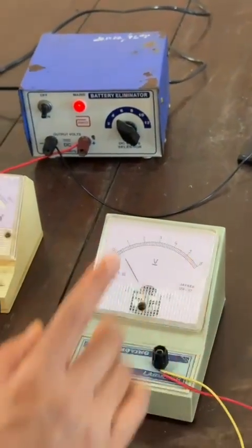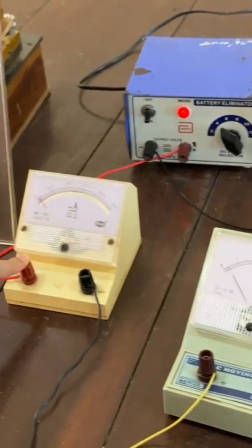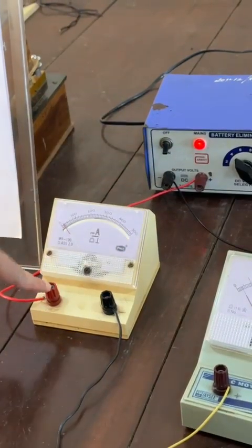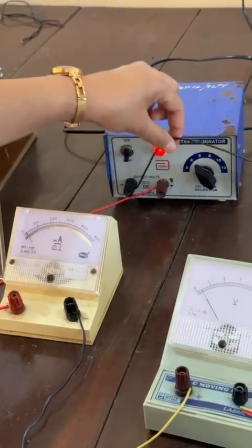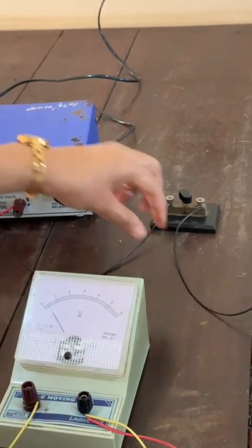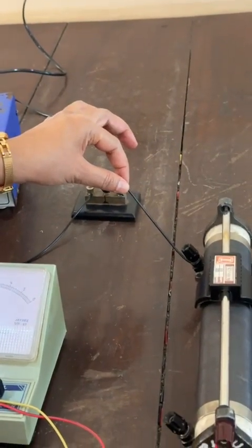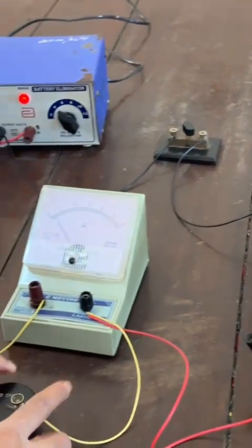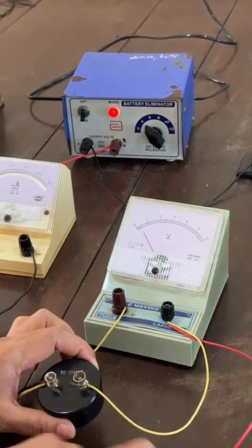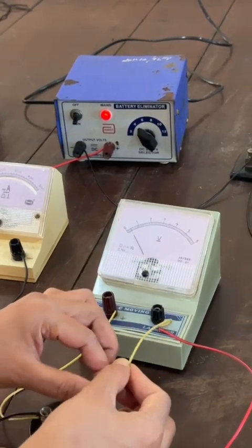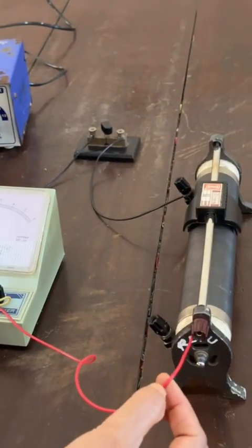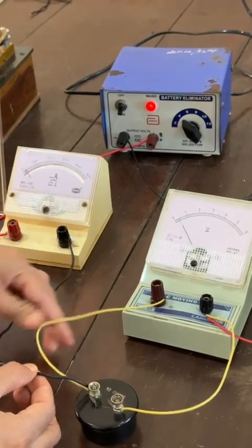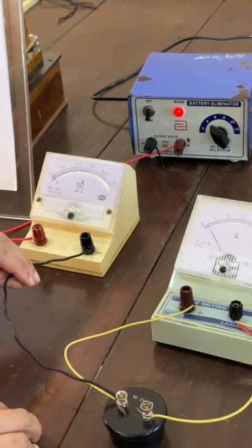So let us see the connection here. From ammeter negative we will start. Ammeter negative is going to ammeter positive, which is going to battery positive. Battery negative is going to the plug key. The other terminal of the key is going to a lower terminal. One lower terminal is kept free here. Then 2 wires are connected to the material wire. One is going to voltmeter negative and another is going to the upper terminal of the rheostat. Then the other terminal of the wire is going to voltmeter positive and the same goes to ammeter negative.